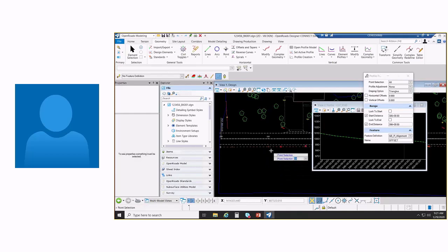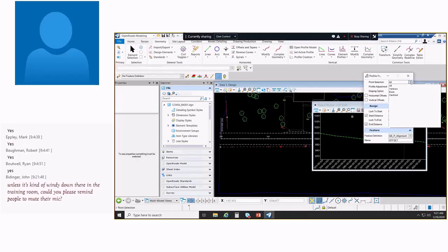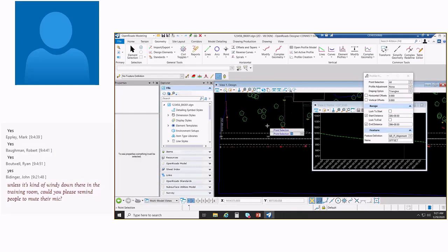Now there's a couple options here that I'll step through. This point selection option should be up there. There's options there, all vertices and centroid. We want it to do all intersections with the terrain. The other options, I don't really see where those would be used. Vertices, ends, or the centroid of the alignment. It's just going to extract an elevation at only the vertices or only the ends. If you're doing something like tying a profile to maybe the top of a head wall or something, then those options kind of make sense. But in this case, we want to do all intersections.